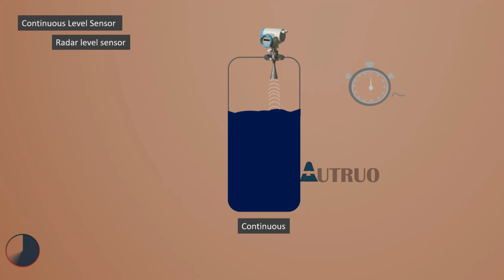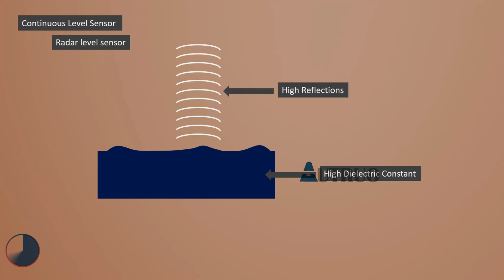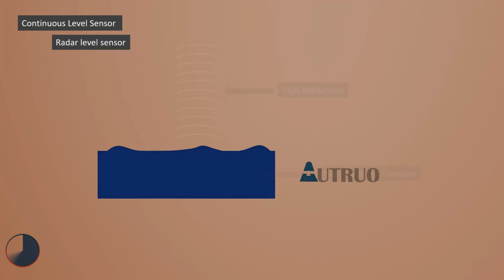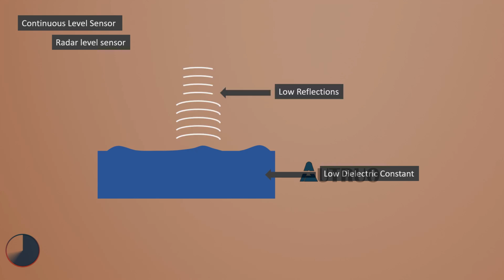One thing worth noting. Before applying the radar meter, the dielectric constant of a product must be known because this has a direct impact on the quality of the reflections. Products with high dielectric constant values will reflect strong and clear pulses. On the other hand, a product with a low dielectric constant value will absorb more of the pulse and reflect less, reducing accurate readings.